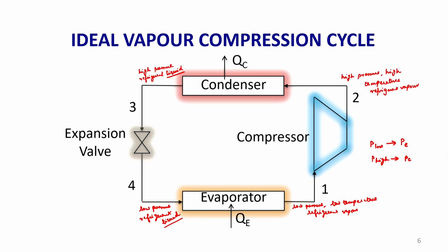The COP of the system is evaluated as the ratio of how much cooling is produced in the evaporator divided by the power required to drive the compressor. Theoretically, or in ideal condition, the evaporator heat load, that is the cooling capacity of the evaporator, and the work of compression, because we use letter C for condenser, so for work of compression I will use CO. CO refers to compressor and C refers to condenser.